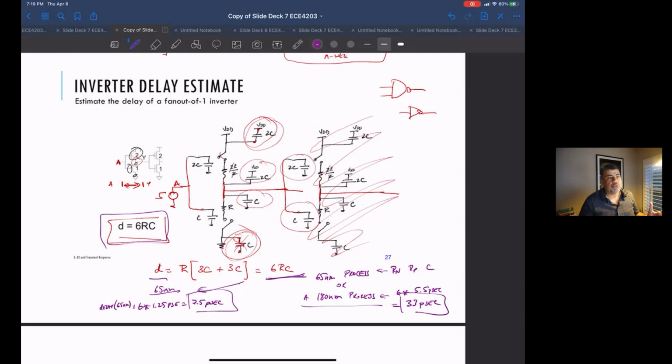So when would you want to do that? Well, when you're designing a chip, you use these things a lot at the beginning of a design project. The first question to ask is, what process do I need to be in? Remembering back to our first or second lecture, a 65 nanometer process is significantly more expensive than a 180 nanometer process. So it comes down to pricing.